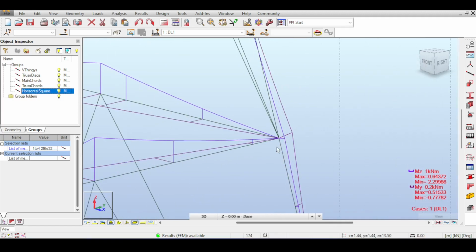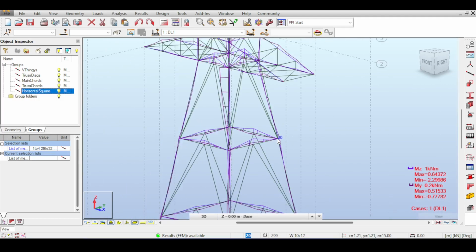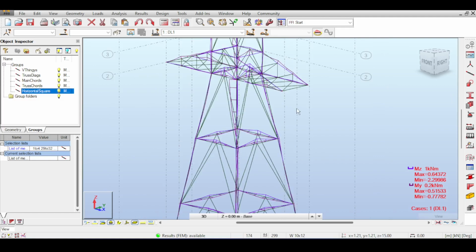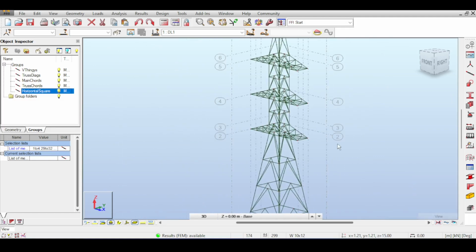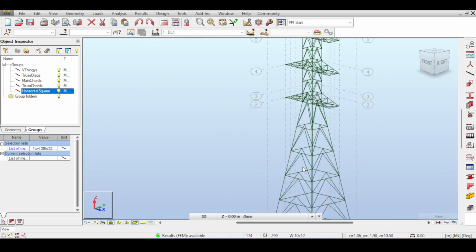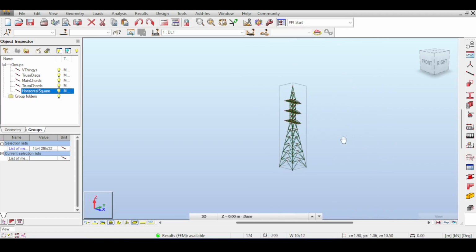You care about this because it has an effect on the connection that you will be designing here, because the connection you will design here is basically a pinned connection rather than a fixed connection. Now, truth be told, Robot is really good at designing connections for normal trusses, but for those trusses, it might fail miserably. So anyway, enough of this. Let's go to the design.